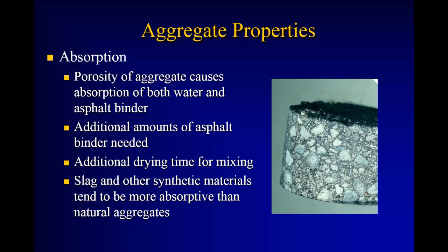So in the asphalt world, though, where it hits us is two ways. Production cost is the first one. I mentioned earlier when the stockpiled aggregate hits the drum, the first thing we've got to do in the drum is get the water out, the moisture out. So the higher the absorption on the aggregate, the wetter the stockpile, the more burner fuel it takes to get the water out before we can even heat the aggregate up. So it's that drying time.